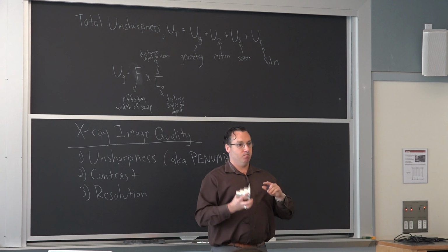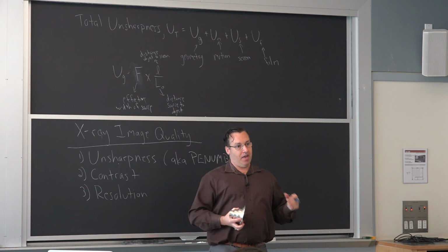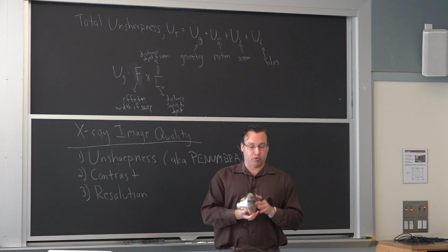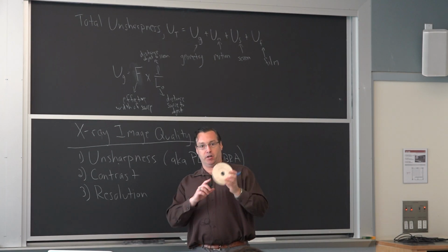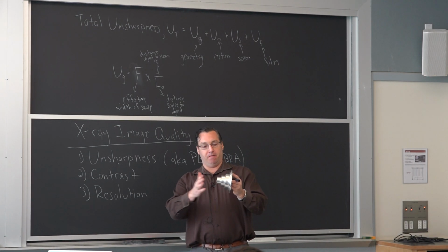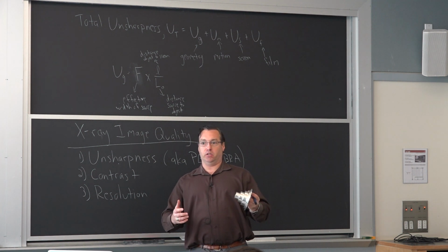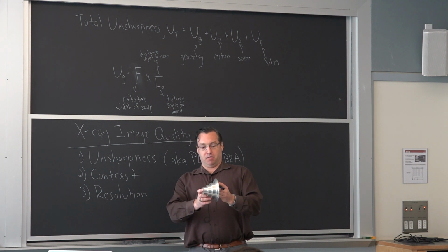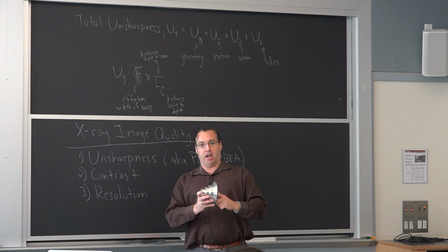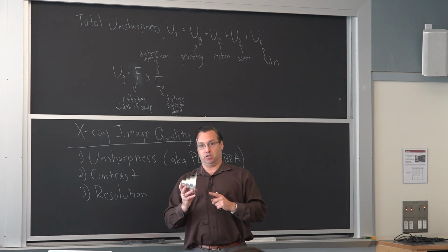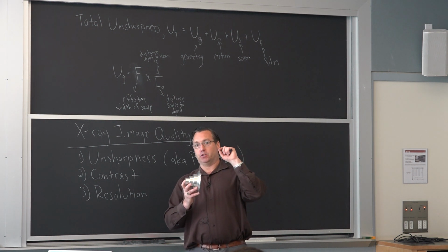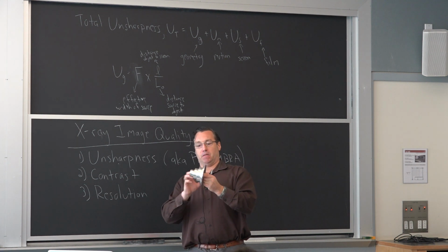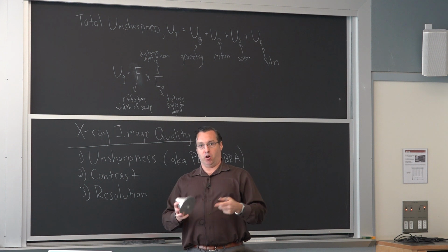That's one of the constraints of X-rays, and sometimes they choose to use ultrasonics instead, because ultrasonics has better penetrating power. If you have a very large sample and it's a dense material, like a steel or a superalloy, the longest dimension is going to be a main constraint on the technique you can use to inspect. So the type of filter you'll use depends on the material, but the main thing is you have to make sure that you can actually scan through the whole part.